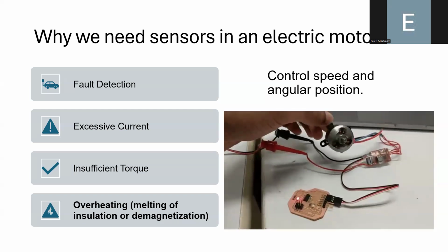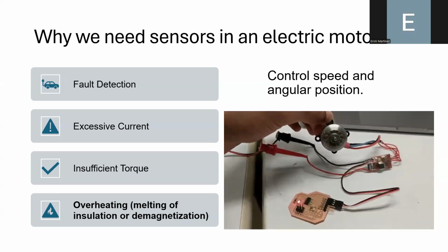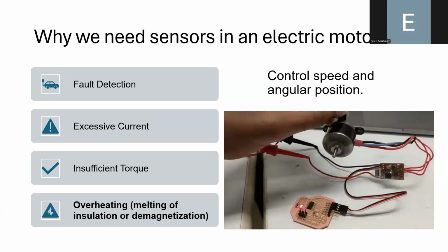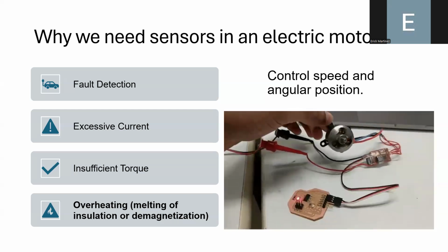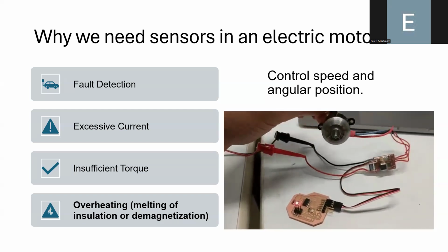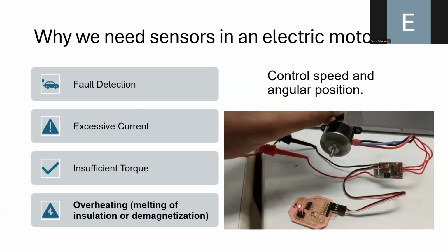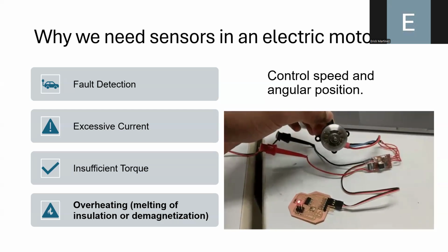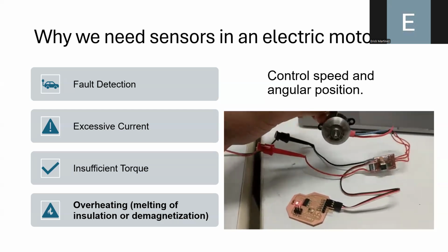of the permanent magnets of the motor. And what is demagnetization? It is basically the reduction of the magnetic flux of the magnets in the machine. And if you reduce that magnetic flux, you will be reducing the machine's torque capability. So the machine becomes useless because you cannot produce movement with it.